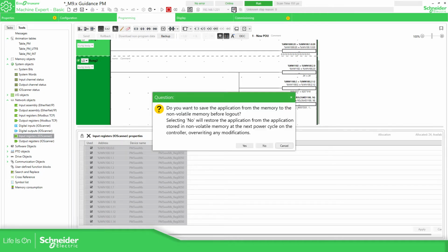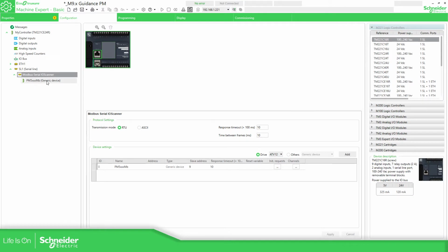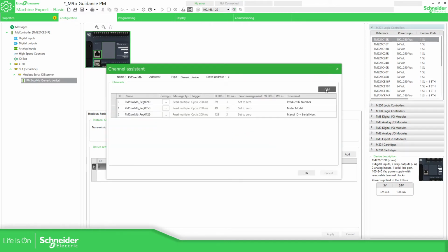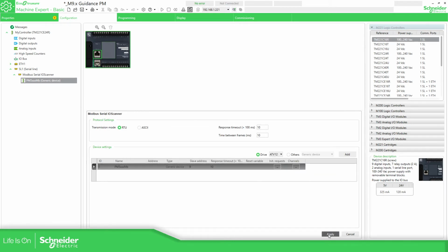Okay, so let's go to the software here. I'm going to disconnect. Configuration over here, channels, add channel, configuration. Here is going to be register 2018. This one is the nominal voltage system. I'm going to read information with 2017. I have already explained this part, and this one is a float variable, 32 bits, and it's going to be 2 words. Okay, apply.